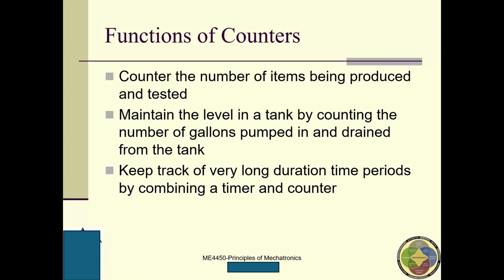The function of counter, as the name suggests, the counter means that they count something. They count the number of items being produced and tested. And maintain the level, for example, maintain the level in a tank by counting the number of gallons pumped in and drained out from the tank. You can just count how many gallons you have pumped in or drained out from the tank. And keep track of very long duration timer periods by combining a timer and a counter. You can combine a timer and a counter together, okay?